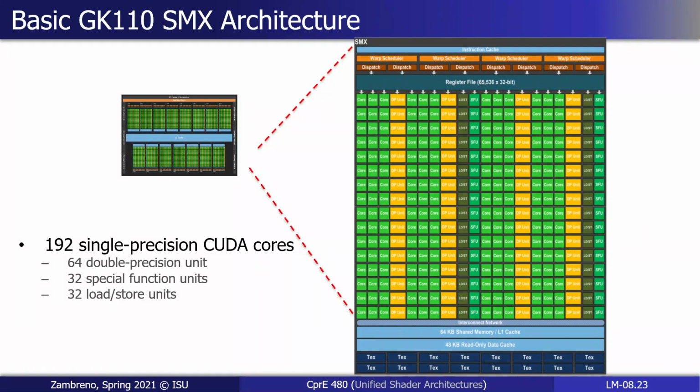Otherwise, it's extremely similar. So you have the individual SM, which is being illustrated here, and there's more of those cores. That decision is something that's changed over time. How many cores in an SM? The trade-off is how many threads you typically would see in a block would then influence how large your SM would be versus having more individual SMs there. But it's a lot of the same. So there's your data cache, there's your register file, and you then have certain units that are your dedicated units. Those are your SFUs. It's very tiny on this diagram. And also this one in the second and third generation has a separate double precision floating point unit versus the regular cores, which are single precision floating point units.